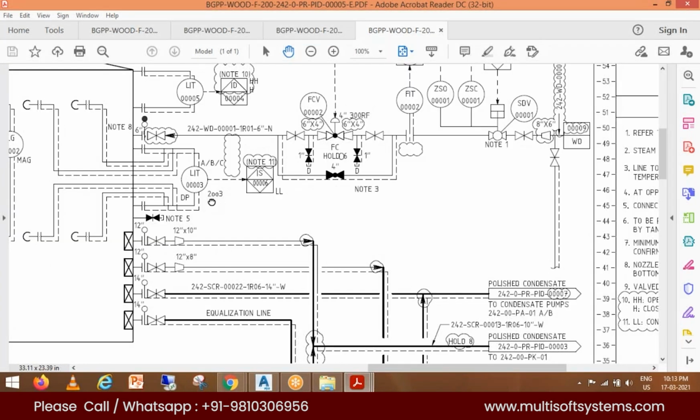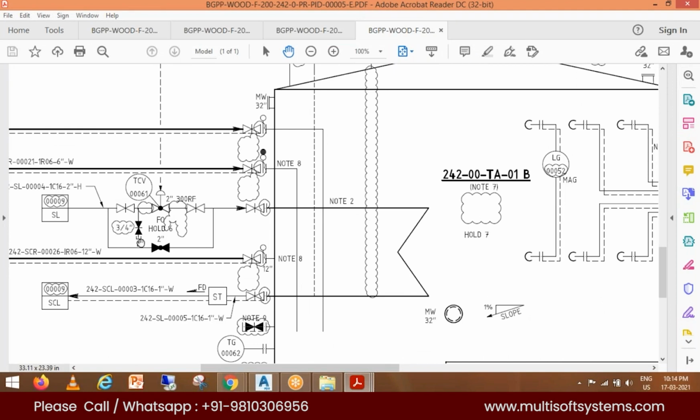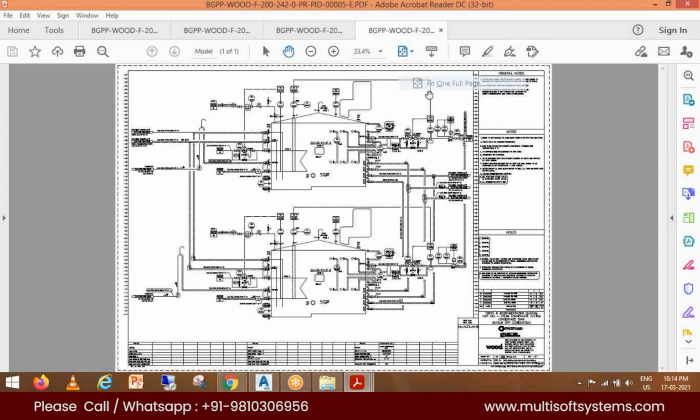And the last one is piping components. Piping components will always be available on the piping. All piping components will be associated with the pipe runs only. So where these pipe runs are, these are all piping components. This is also a piping component, and this is also a piping component. So these are the four major components of a PNID: equipment, instrument, pipe run or pipeline or routing or fluid runs, and piping component. With these four major components, your whole PNID will be drafted.